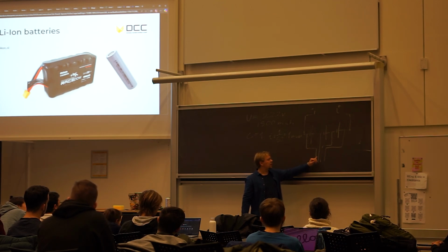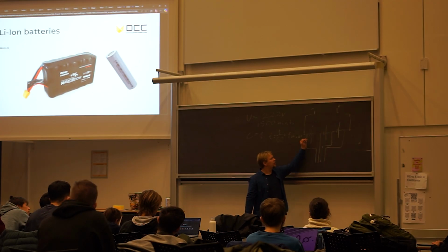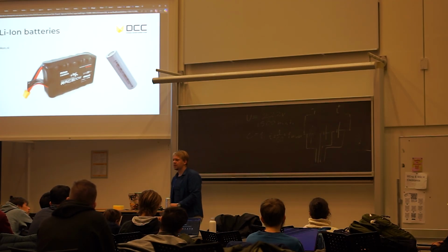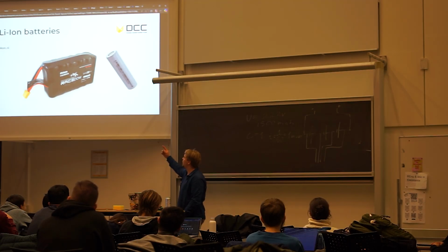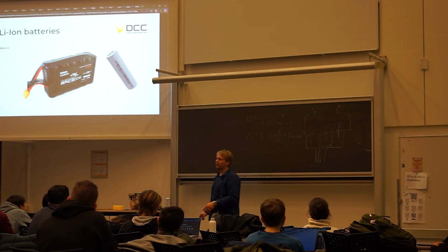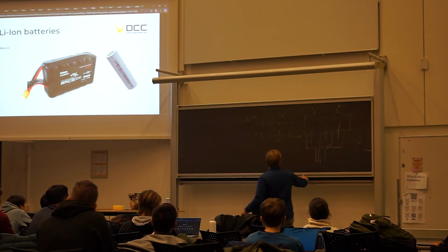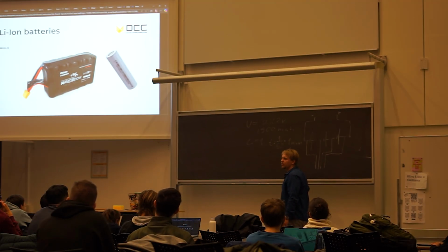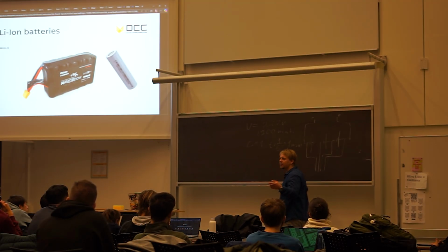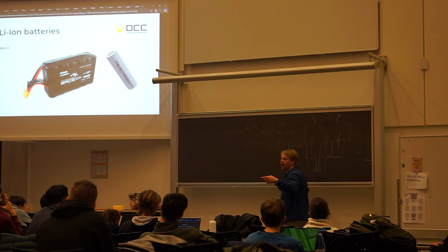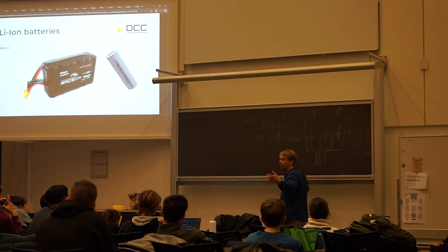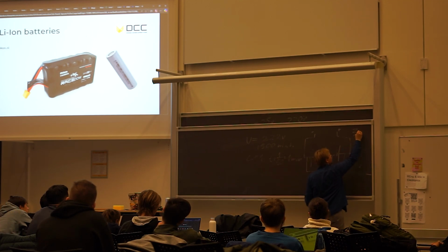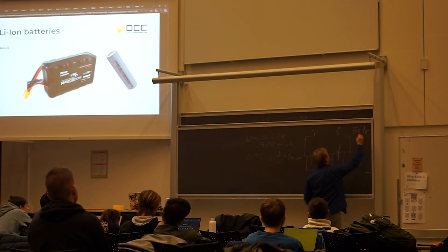So you can see here that you can measure the potential across each cell. The battery that you see in this picture, also battery configurations, is a 6-cell 2P. That means it has 2 cells in parallel. If you have cells in parallel, you don't have to balance charge those. Right now this is a 3S 1P.